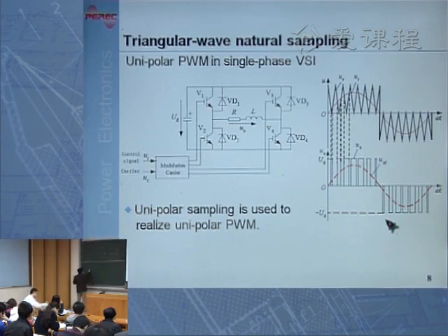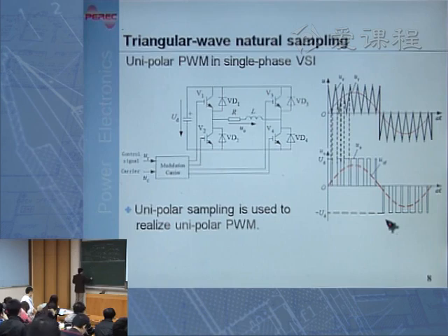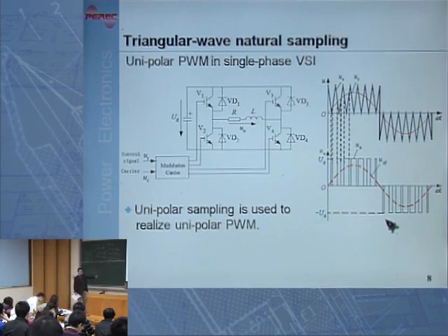So if we were still using the square wave voltage source inverter, let's say generating a 180-degree square wave, this is the load voltage, and it is far from sine wave. If you do Fourier series analysis, they do have fundamental components. Okay, these are the fundamental components, but it does have a lot of harmonics, right? It has third, fifth, seventh, ninth harmonics, all harmonics there. It is far away from sine wave. So that is not good.